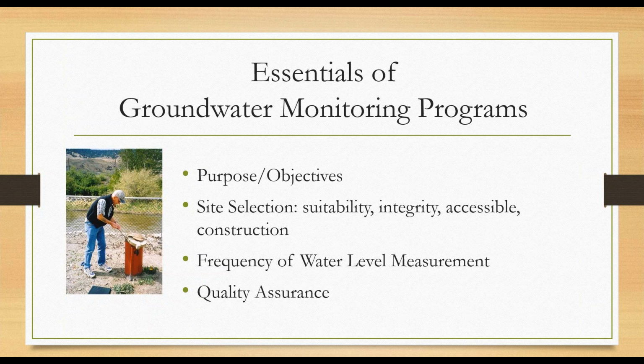You want to make sure the sites are suitable, the wells and what you're collecting data from is good integrity, and we'll talk about how we verify well integrity. You want to make sure it's accessible. Can I get in and out of my site with no problem so that I can collect the data as frequently as I need to? And construction. You want to make sure that the sites that you select are screened or open to the proper aquifer, are in a location where maybe it's along a flow path that you're interested in, but you need to know a little bit about those sites before you make a selection and include them in your study.